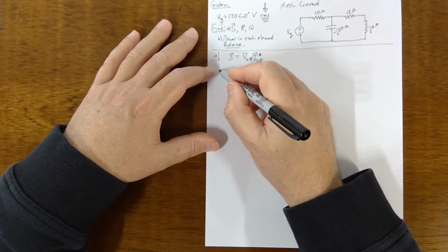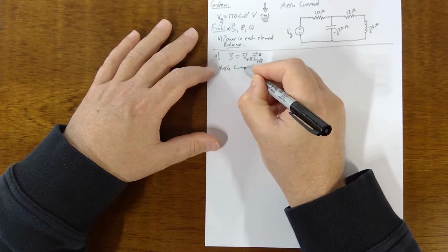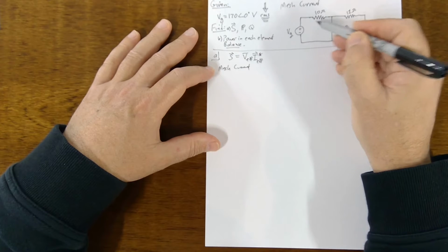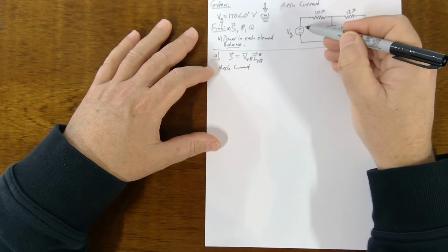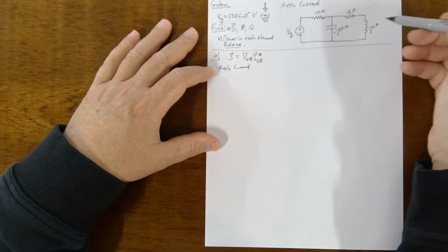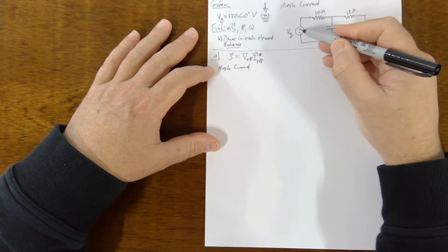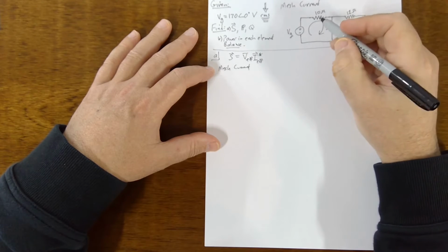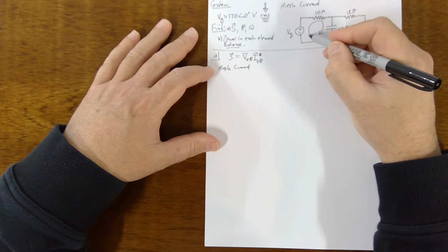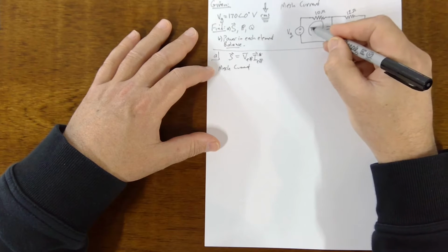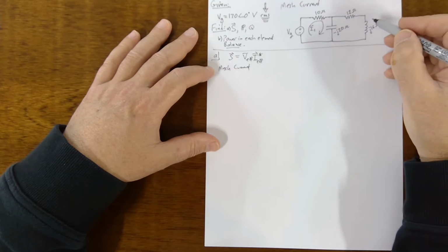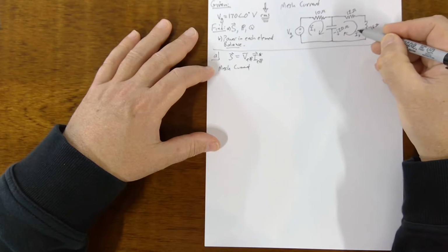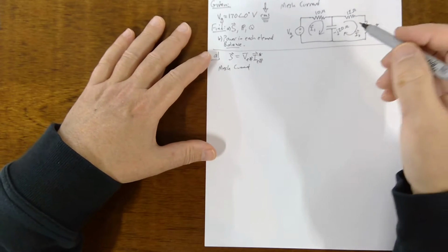So we're going to use mesh current here. We need to establish some mesh currents. There's this plus symbol. It doesn't really mean anything in this particular circuit. You'll see in the next chapter where this will have some significance. But for now, we can just choose any direction. You might as well agree with the plus like we've been doing in chapter 4. So we'll call this I1 mesh and go around the same direction and call this I2 mesh. And these are phasor mesh currents.